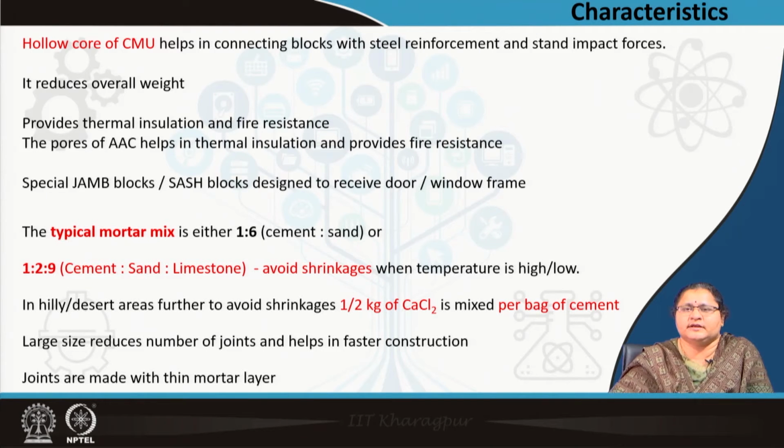As I told, it is not completely dry. Yes, it has an application of mortar similar to that of brick, and the mix is 1:6, the cement sand ratio of the mortar, and the joints are very thin. In high temperature, to avoid shrinkage, an addition of lime may be added.